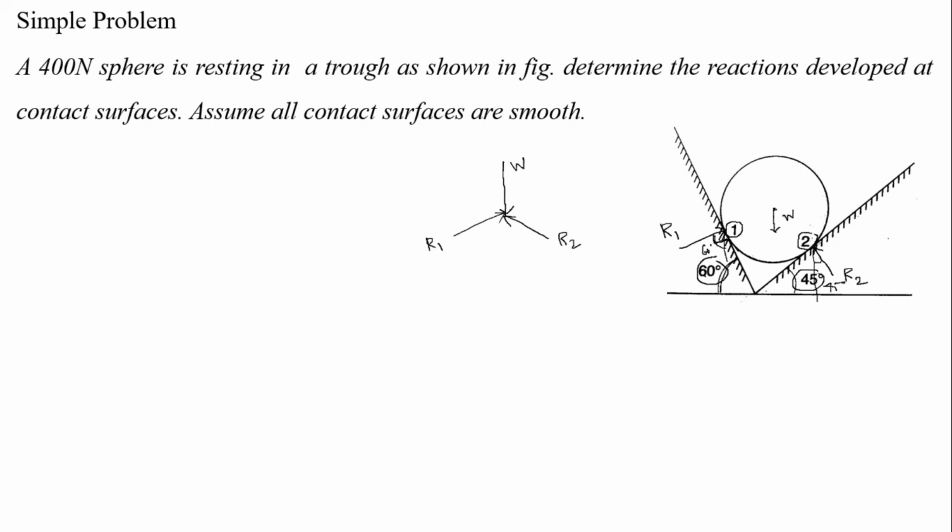Now, draw a vertical line, right. So, what is the value of this? This is equal to 45 degree, right. And this is equal to 60 degree, right. Now draw a horizontal line. We know that the included angle at the bottom is 180 degree. We know that this is 90 degree and this side 90 degree, so we have to find this and this, then only we can calculate the included angle between W and R2, W and R1. So 90 minus 60, 30. So this side 30 degree and this side 45 degree, 90 minus 45, 45, right.